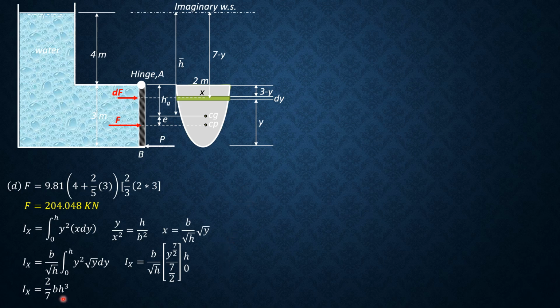So knowing that Ix is 2 over 7 bh cubed, and the distance between the x-axis through the vertex and the centroid is 3/5 of h, by the transfer formula, 2 over 7 bh cubed equals I sub cgx plus the area of the parabola, 2/3 bh, times the distance 3/5 of h squared.